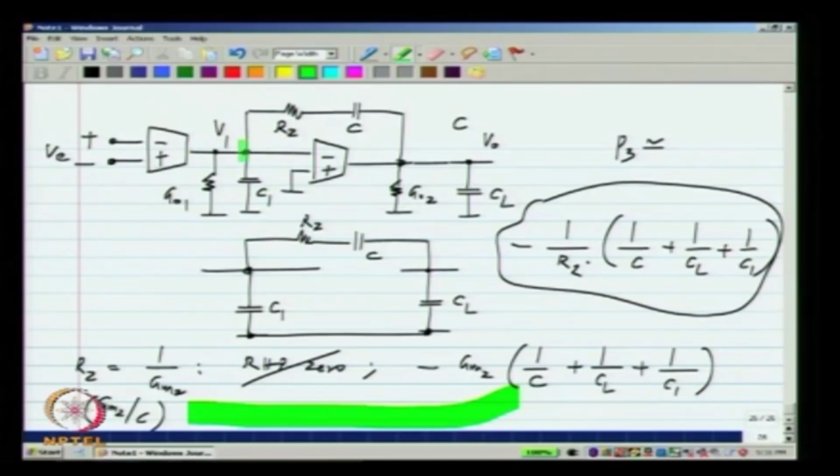And the extreme case, when let us say RC is infinity, then you will not have this capacitor here at all. You will have these poles very close to each other. Earlier we saw that when this branch was not there, when C was not there, there was some pole frequency here and something else there, and when you introduce C, they moved further apart, which is good for stability. Now, if you make RC equal to infinity, that is very large, then you will go to the original case where the poles are relatively close to each other, which is very bad for stability. Okay. So, it is not a wise thing to make RC very large.